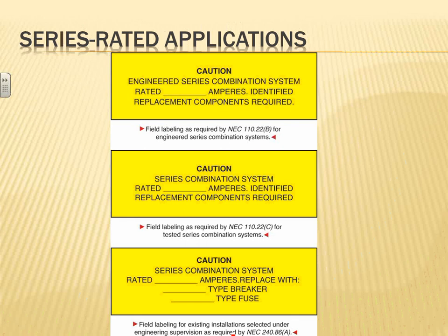So as you all know, SPD guys have tons of tables of which fuse goes with which to get your circuit rated. And as a matter of fact, they have fuse to circuit breaker series rating. So this is under engineering supervision. If you're a registered engineer, you have the capability of doing them in the field.